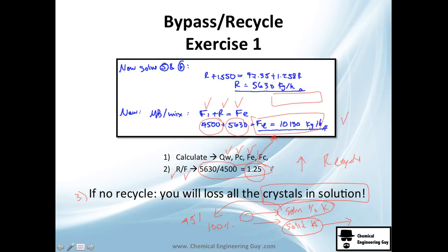So this depends a lot on the process, the products, what you want, etc. But in general, a good recycle ratio will be something about 120 to 180. But I'm telling you, you need to know the process. Maybe they tell you 5,000 times the recycle, which is crazy, but maybe it works. And if it works and makes money, it's fine.